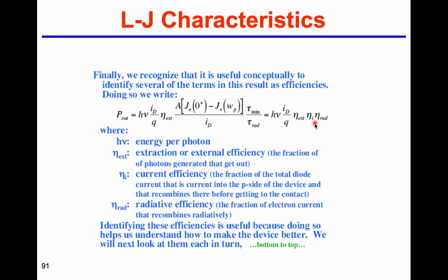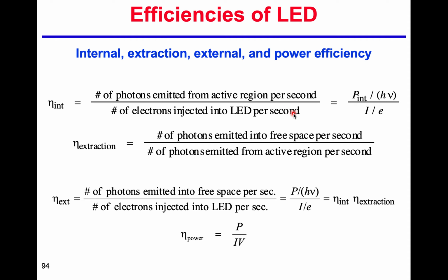So this term is related to electron-hole recombination. We need to have a higher eta_I, of course. It is possible to approach 100%, and also the radiative recombination. Which means we need to reduce the traps, reduce the non-radiative recombination, and improve this one. Okay, so that means the output is almost linear to the input, ideally.